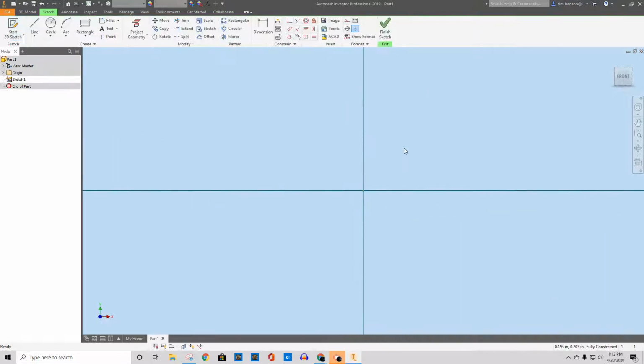Now, one thing that I didn't understand when I started modeling like this, I just modeled anywhere, because you can model anywhere. But I try to remember where my origin's at and base most of my stuff off origin. That helps me keep track of things later, especially if I'm doing cylindrical objects. I always want that origin in the center of my cylinders. It makes it really easy if I ever have to go on a plane to divide it or make a flat plane going across it or something. You'll understand that as you get going.